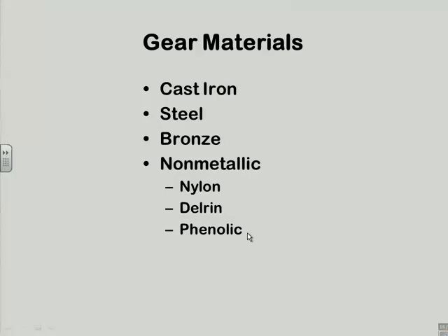So they're very expensive with these alloys because only a couple of companies make them. Rulon is one trade name. I've used them in many applications, and they work quite well. And the big deal with those is you can run them dry with no lubrication, particularly if you've got the molybdenum disulfide and the graphite in there, because that's self-lubricating.